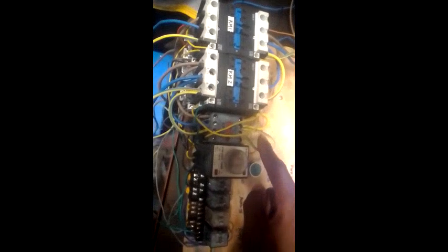It starts. You can see, it has switched. Like I told you. Watch. Let me stop it. At first start, the main contactor and the start contactor starts. Then after a set time, by this timer, feels like a few seconds, it will stop the start contactor and engage the delta contactor with the main contactor.